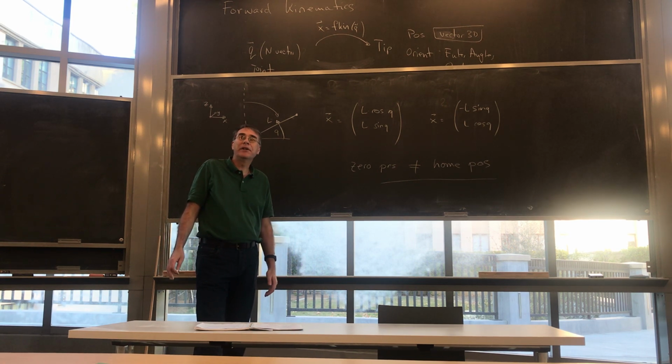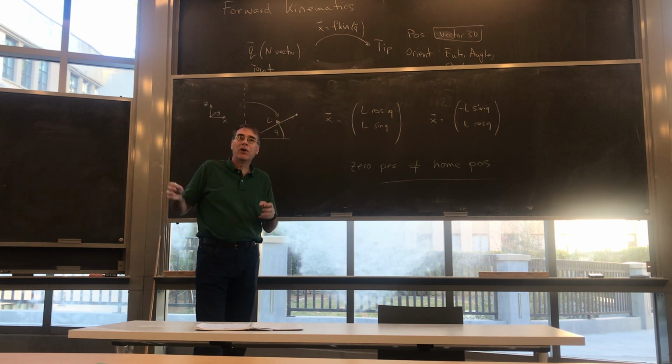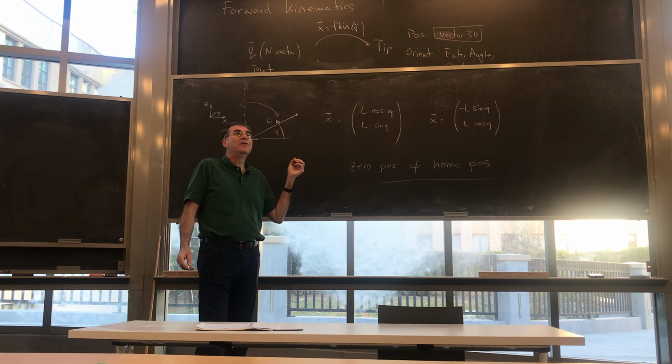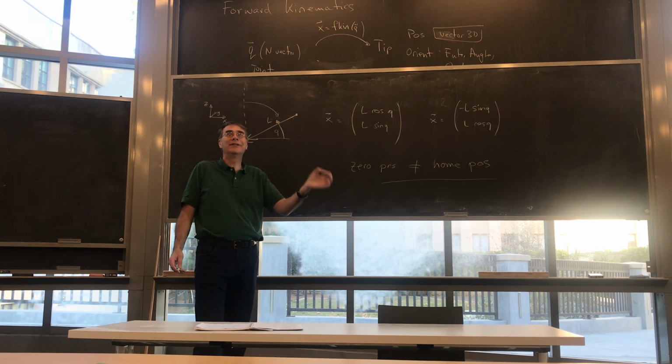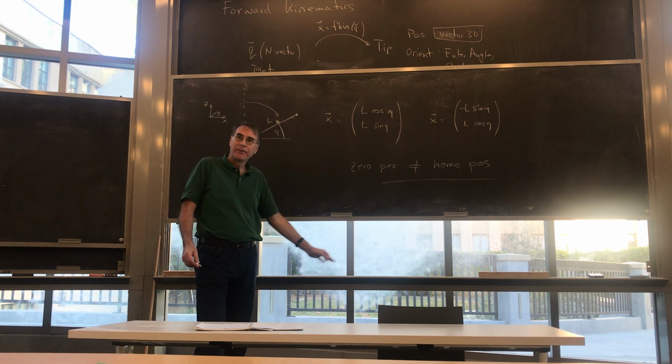Right? And so normally you start your robot up in a certain configuration in its sweet spot, and it's nominal. So usually that I would call the home position. That's where it wants to live most of the time. That is not necessarily the same thing. Given that everything initializes at zero, a lot of times it's convenient to pick a zero position that happens to be basically where you want your robot to be, but it's also arbitrary.